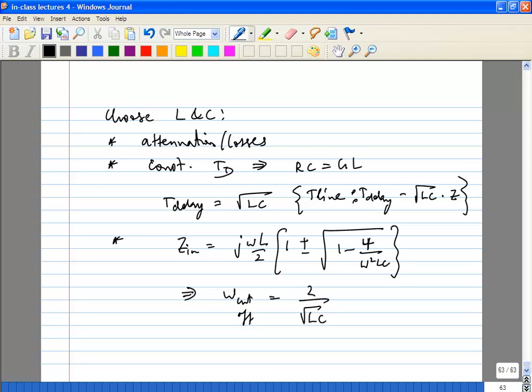So where would these kind of amplifiers be used? You typically use them in cases where power is not a concern, because these distributed amplifiers are very power hungry. The other thing to remember is that the noise figure of these amplifiers will also be very high, and obviously the area would be very high.